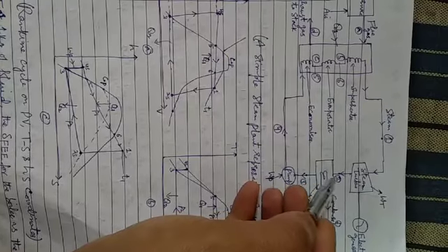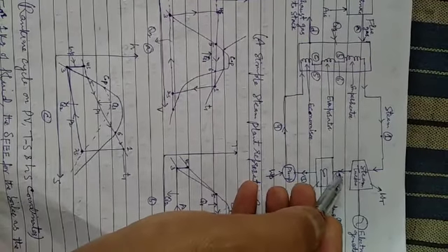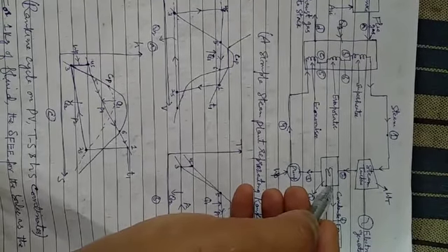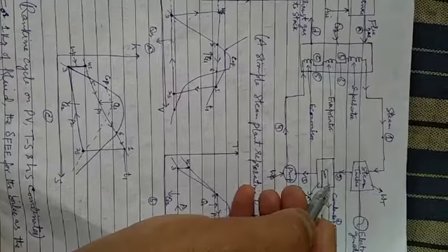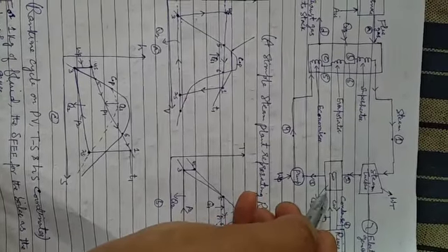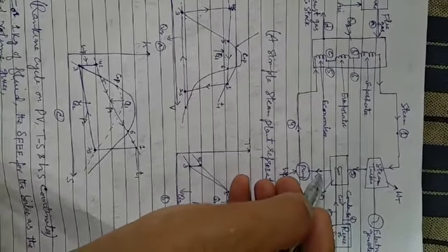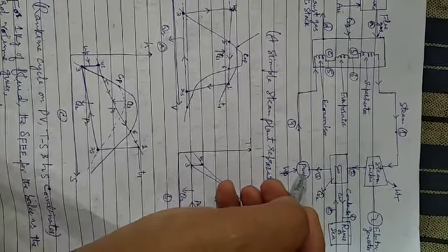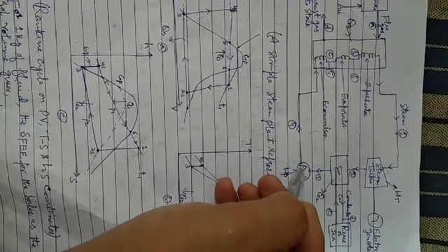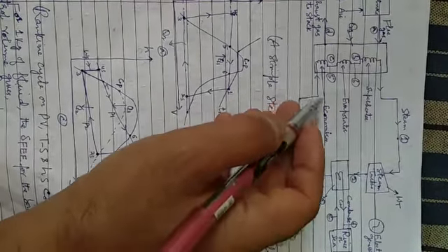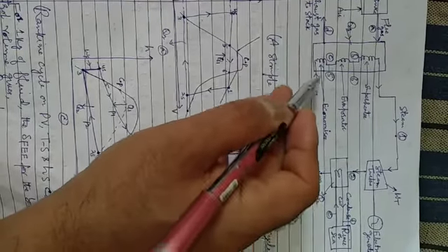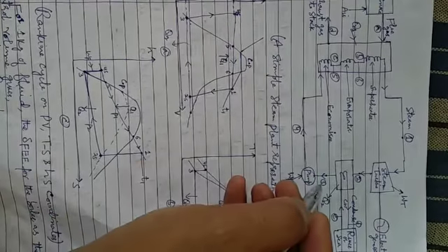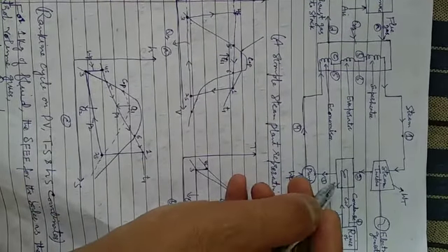After point 2 comes the condenser. The steam enters the condenser, and the condenser converts this steam into liquid, that is, water. After condensation, point 3 is marked after the condenser. Then the liquid enters the pump, whose function is to lift the liquid back to the boiler. After the pump, point 4 is marked, and point 3 lies between the condenser and the pump.